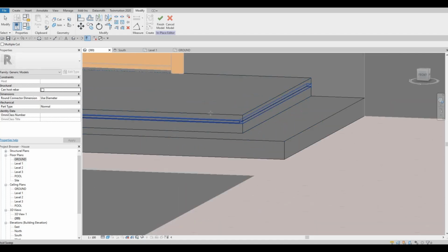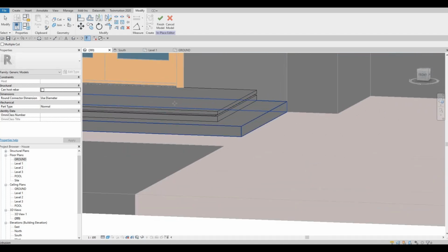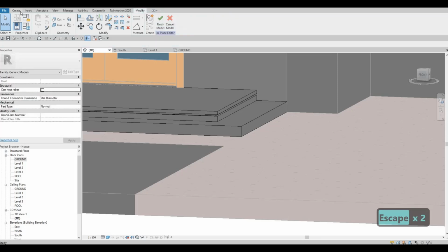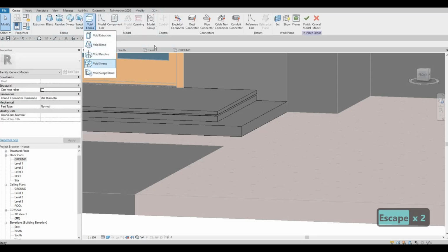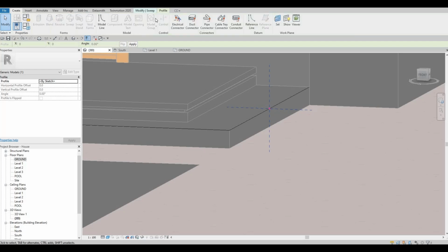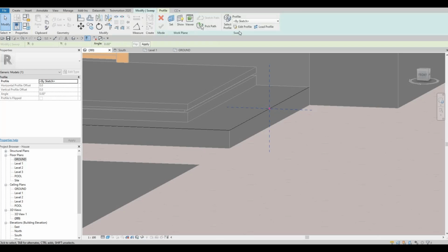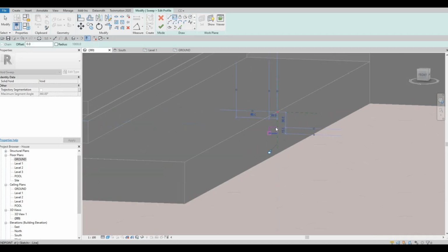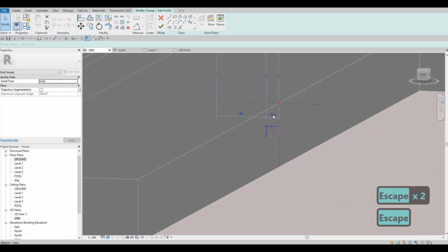So I'm going to put in lights there, LED lights, and then it will look nicely on the image. And then we're going to do it here as well. Create void sweep, actually, not extrusion. And then here pick path. Let's pick all of this right there, and then edit profile, use this, and I'm just going to gauge 15 by 25.